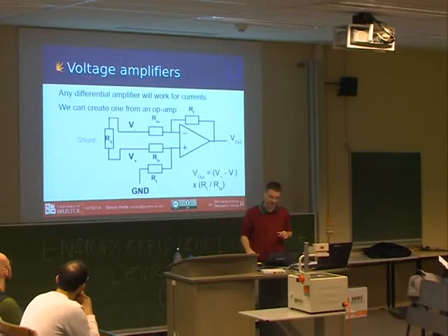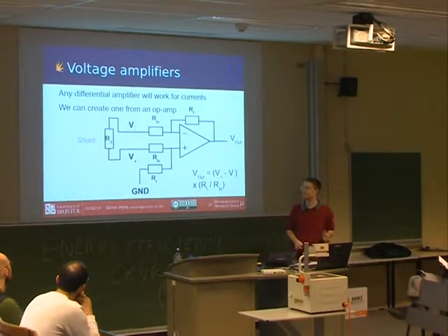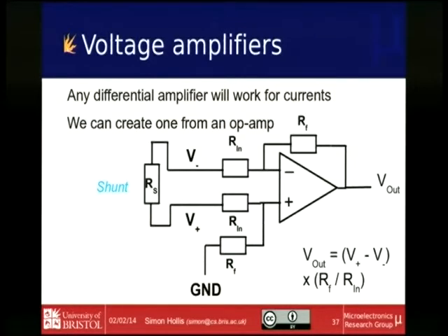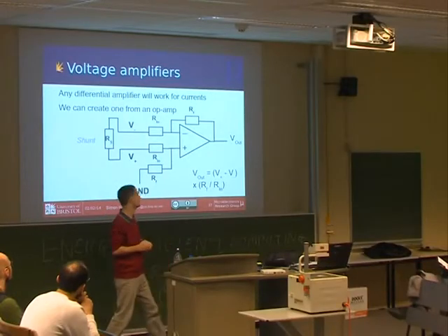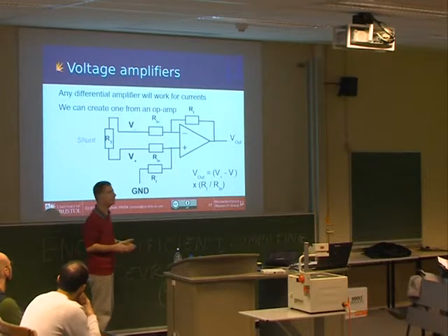Well, that's the stuff of electronics engineering students the world over in their first year. You can use a device called an operational amplifier. It's well known, well tested, very easily available off the shelf, and you build exactly this circuit. You've got a differential input and an output, and then you add in this thing called feedback, which gives you the amplification.